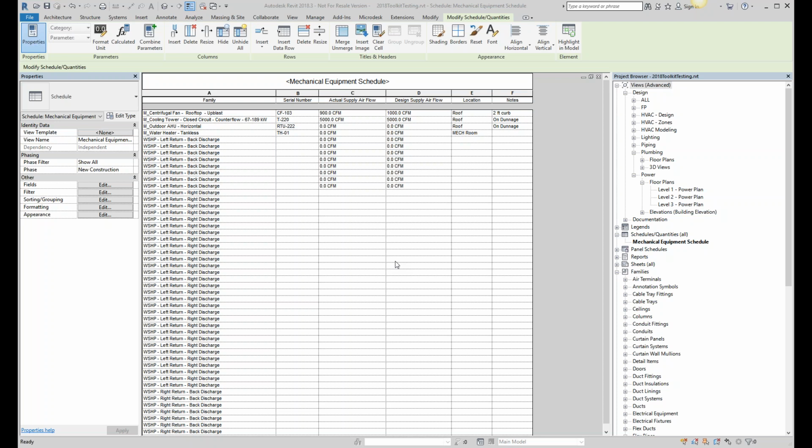There is a question about why we don't recommend using project parameters for certain categories of objects, and Will did answer it in the chat, but I'll elaborate vocally. Project parameters are really good when you actually want a parameter on every object in a category. But something I've become sensitive to over the years is as you start to use more and more Revit schedules and add parameters to the objects that live in those schedules, you can end up polluting other Revit families in your project with parameters that aren't relevant to them.